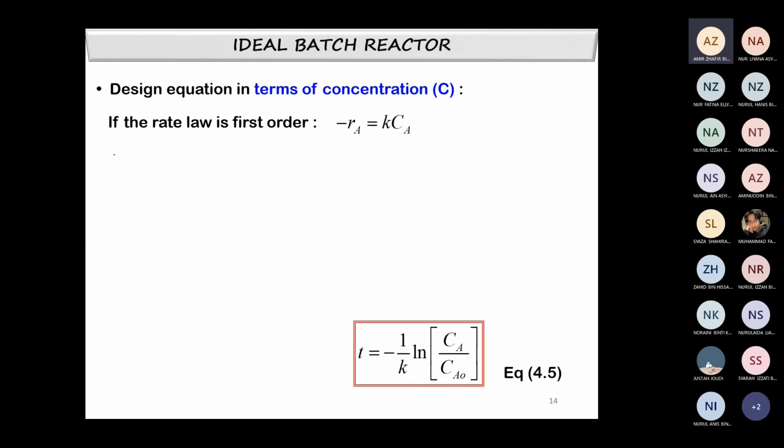Okay, I will slow down a bit. So from the mole balance, remember we already simplified it. Let me write the mole balance here. What remains for this batch reactor is rAV equal to dNA over dt. This is the accumulation, and this is the generation, which is the reaction. So from here we put dt on one side, bring it up.